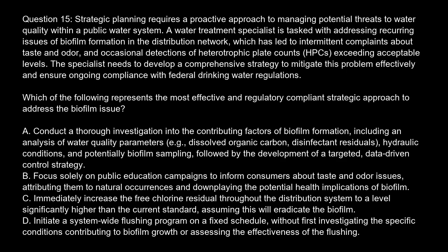Option C. Immediately increase the free chlorine residual throughout the distribution system to a level significantly higher than the current standard, assuming this will eradicate the biofilm. Option D. Initiate a system-wide flushing program on a fixed schedule, without first investigating the specific conditions contributing to biofilm growth or assessing the effectiveness of the flushing.